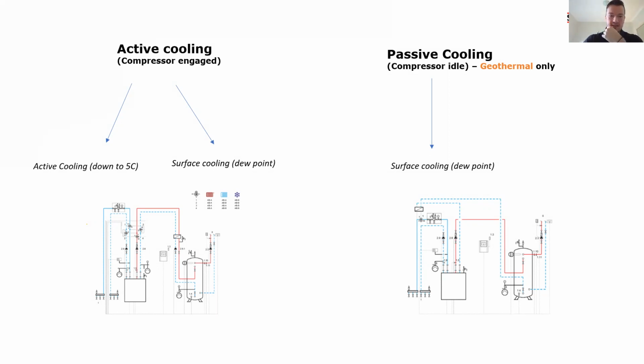Passive cooling, and the schematic here is for geothermal heat pumps. The air source schematic would look exactly the same. That's why we decided to not post it. The geothermal install would require a good amount of valving, up to 4 valves essentially. And again, we'll get into the nuts and bolts of that in module 2. But we would use a couple of valves essentially to just swap in passive cooling, just swap the energy from the building envelope with the cooler energy in the soil. So these would just reverse flow direction, if that makes sense, in a passive state without the compressor being engaged.